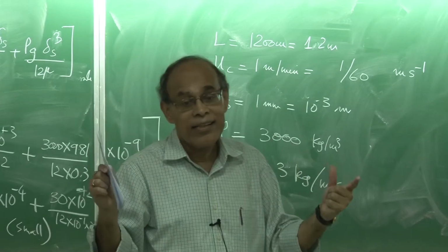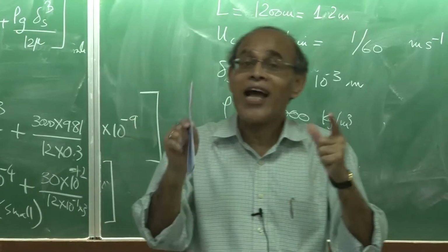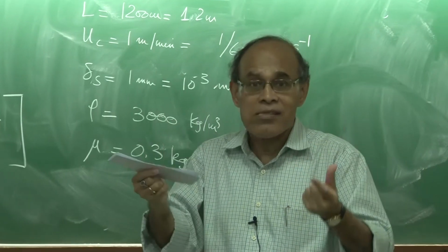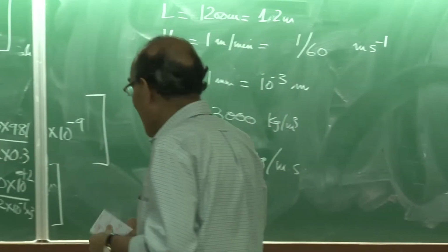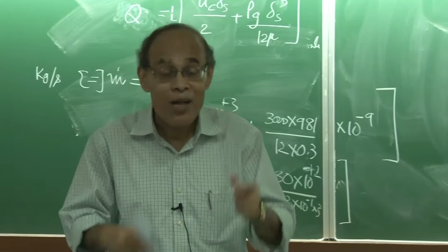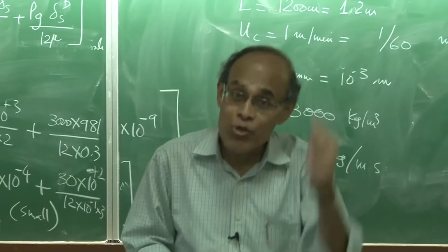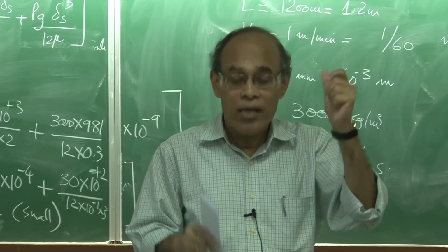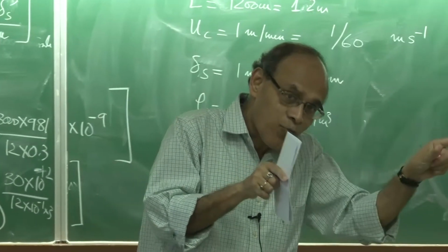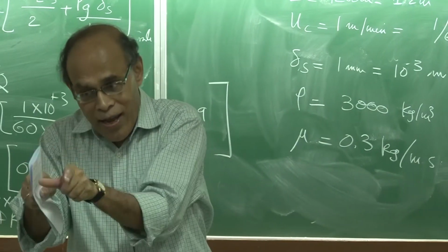And as I said, to do a real life analysis of flow within the film, one has to deal with the subject at a much more complex level, and that perhaps is not within the scope of this course. It has not yet been amenable to very advanced research because of the many phenomena involved in the whole process, including the reciprocating motion of the mold, the downward motion of the strand, and solidification. The powder in contact with the mold surface is solid. On the other hand, the powder in contact with the liquid in the solidifying casting is liquid.